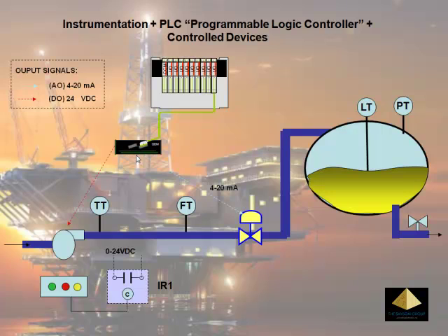Another output, this is going to open and close the valve from 0 to 100%. So this is actually an analog output in 4 to 20 milliamp current range. And another output, this time it is a valve, which actually is a solenoid valve, which just opens and closes the valve. So the electrical format is actually 0 and 24 volts. So now we have covered the outputs.